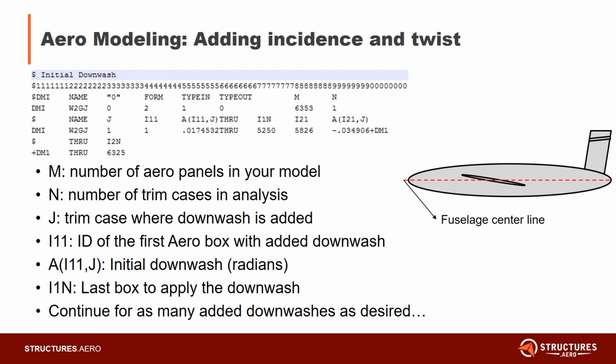Now, one of the really important things that comes up when considering a full aircraft is, take this picture on the right. It's a really silly image I drew up, but say we have some conventional aircraft. At cruise, we'll probably want some positive angle of attack on our main wing so that we're generating enough lift to fly, right? And simultaneously, we know that we have to provide some downward force from our tail, which means it should have some negative angle of attack.